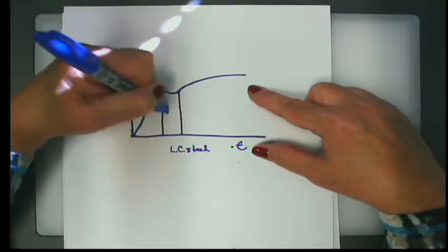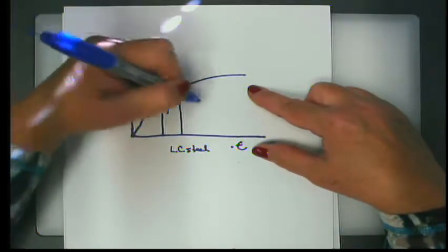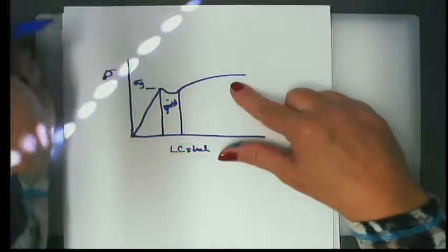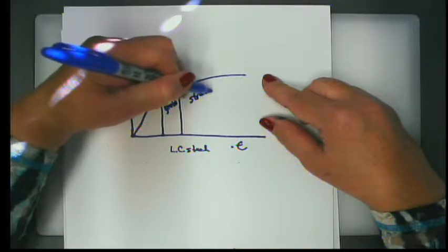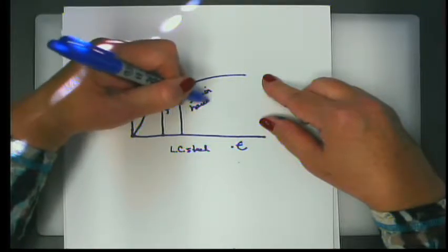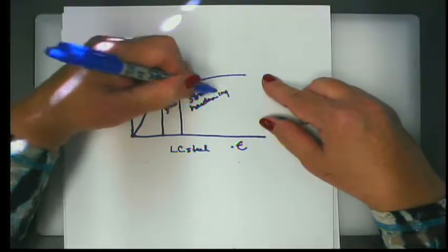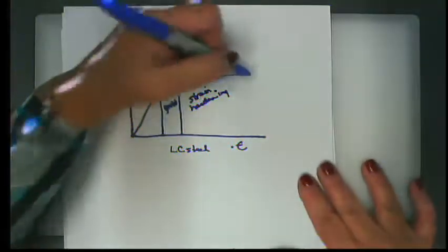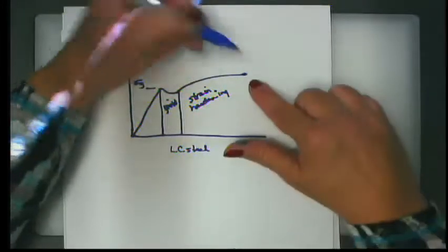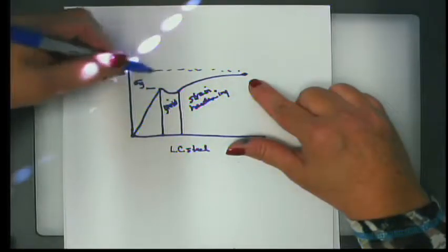So this section is referred to as yield, and where it needs more stress to continue elongating is referred to as strain hardening, because it feels like it hardens a little bit at that point due to either the stress or the strain. And at some point you will reach sigma ultimate, which can be above sigma yield.